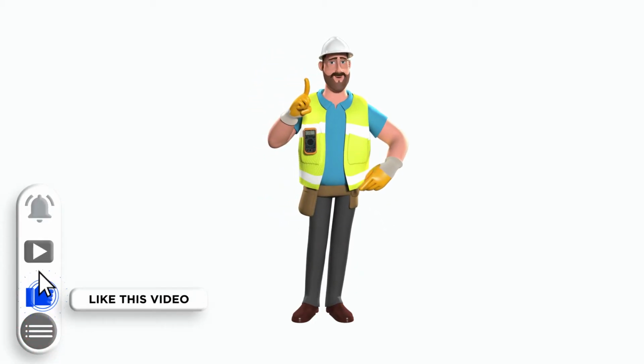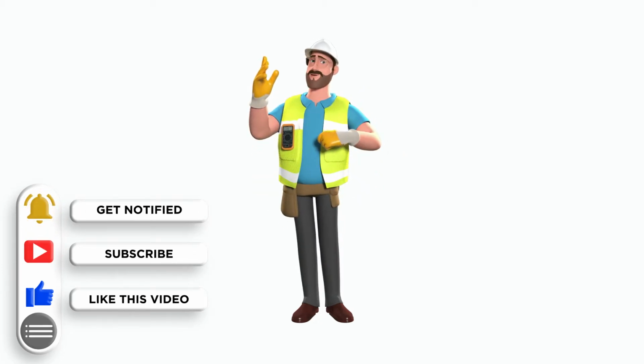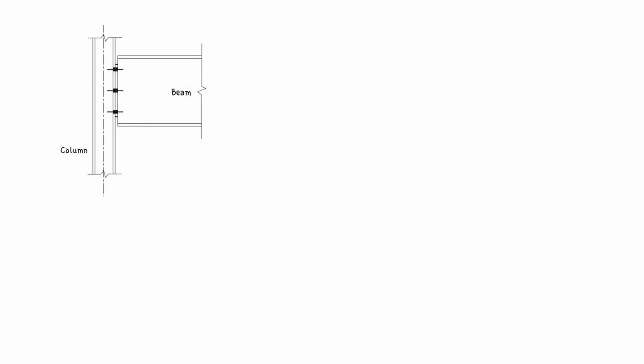In today's video, we will be showing you how to calculate the axial force and the moments for a column that needs to be designed. Simple beam and column construction refers to a multi-story building structure with the following characteristics. The structure consists of beams and columns, where the beam end connections are assumed to be pinned. Lateral stability of the building is provided by masonry or concrete cores, or vertical bracing. In other words, no bending of the columns.